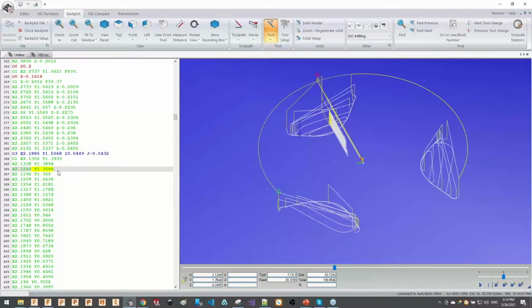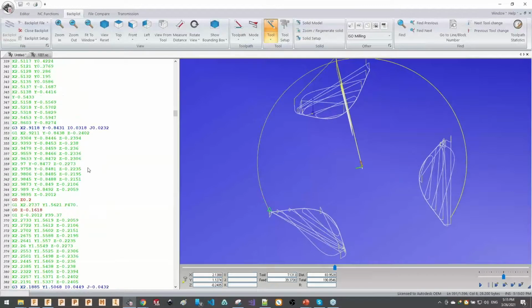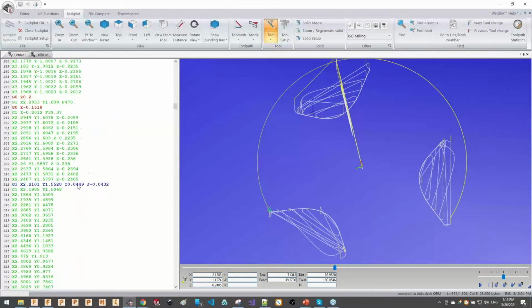But let's suppose that you did try to run this. So I go to the shop floor, I try to run this operation, and it returns an error saying that, hey, the y-axis is out of travel. You don't have enough travel. It could be due to the y-axis or it could be due to the x-axis. So we need to switch that into a polar mode. So how you can do that?